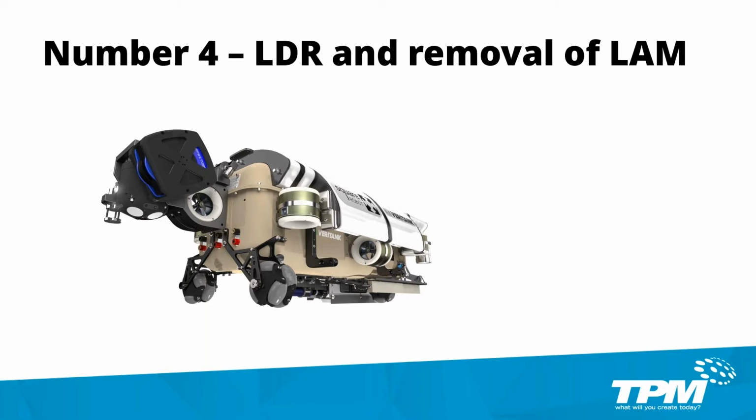Now that we don't have that limitation of the RAM that we were limited to using, we can use more RAM. Our computers are more powerful than they've ever been before. And since we're still only using that single core, we can still use the more powerful processors that are out, and we can actually kind of remove the throttle limiter on LDR mode. So with the 2020 version, you'll notice that the large assembly mode, which is also kind of part of what we use for our large assembly settings, is replaced with a button that just says large assembly settings.